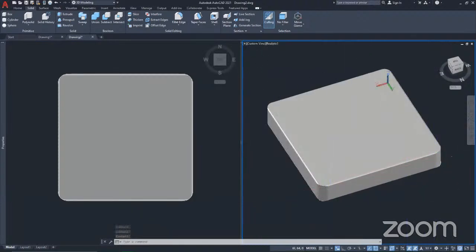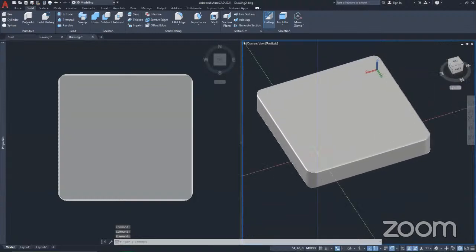Okay, so we're going to continue again. And this time I want to create a space inside of this box so they can fit in the electrical part of it. Yes, the part that is actually making the device work. So for that, I'll use the shell command. This shell command will create a shell covering an empty space, just like your matchbox. The box is covered, but inside is hollow. So the shell will have a thickness, just like you can add a thickness to a surface. So that's what we're going to create now.